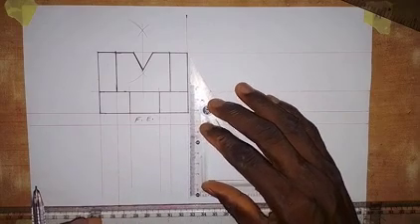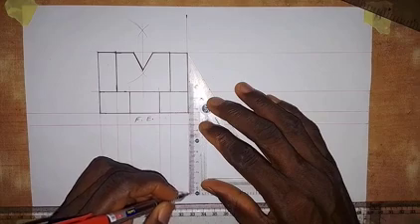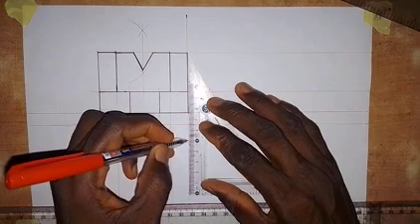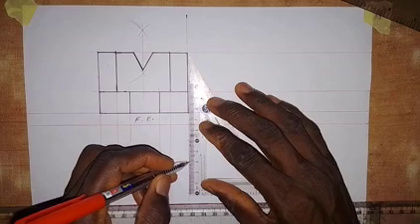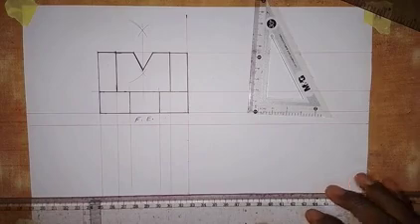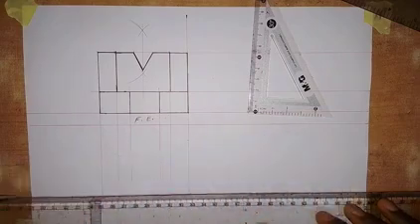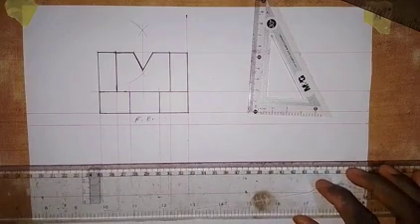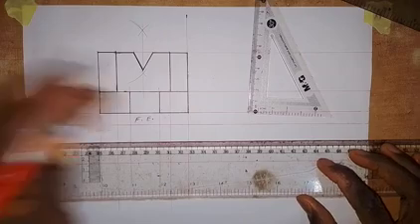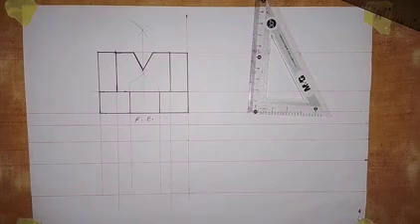So I will now take a measurement of this 65 millimeters. So this is 65 millimeters here. So I will come here and take that 15 at once, okay. Then I will take 30 millimeters in, so this is 30. On each of these points, I'm going to draw a horizontal line, like this. So coming to this point, I will draw a horizontal line, and then at this point, I will also draw a horizontal line.